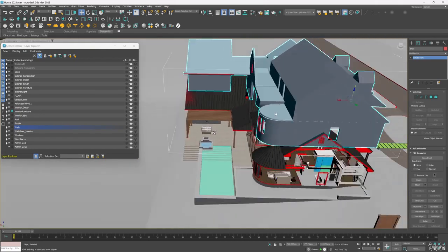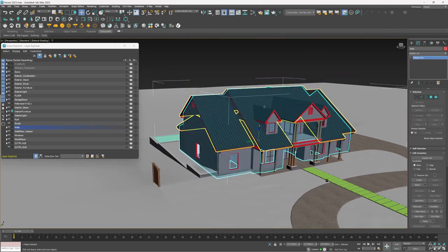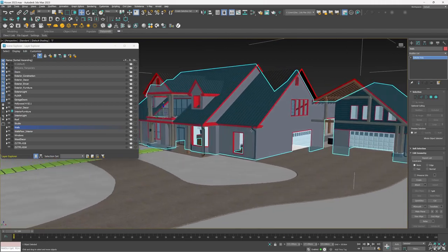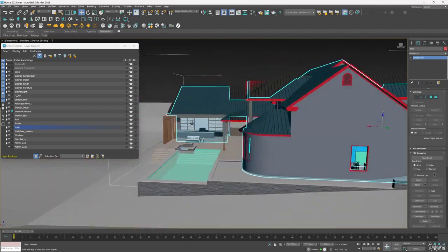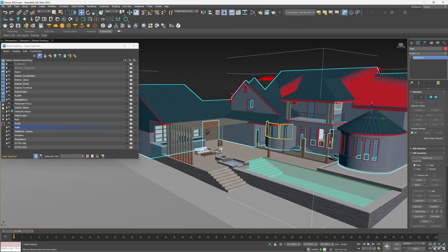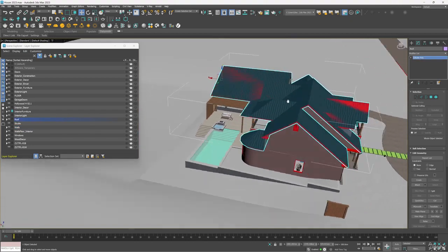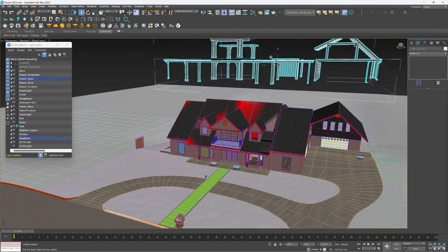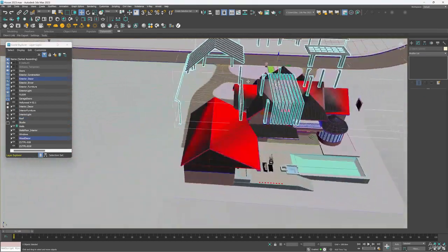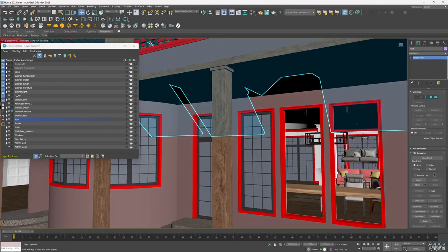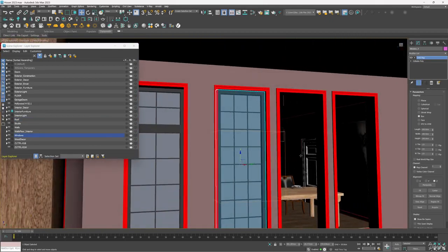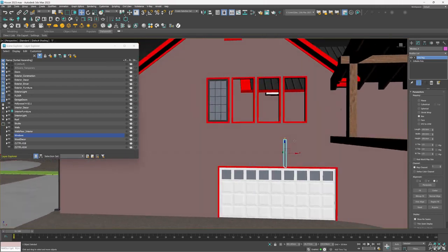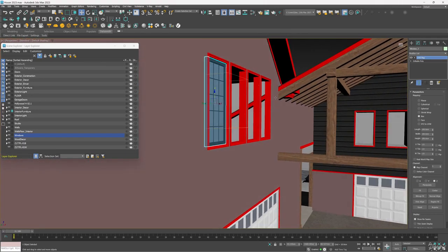I merge all the walls into a single mesh for better optimization. By the way, as a single mesh is how your client can transfer the 3D model to you when exporting from SketchUp, Revit or Archicad. All elements of the roof are merged into a single mesh, as well as facade decor elements and some other small objects, for better optimization. Windows are not everywhere. For better optimization, assets with multiple copies should be duplicated in Unreal Engine. I'll show how this affects performance in the next part.